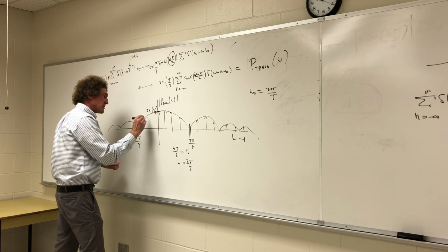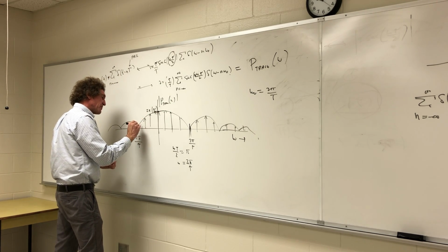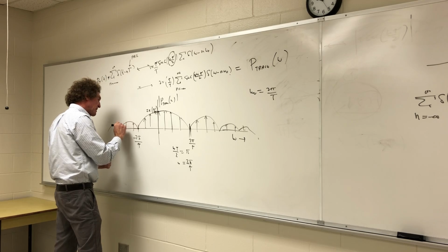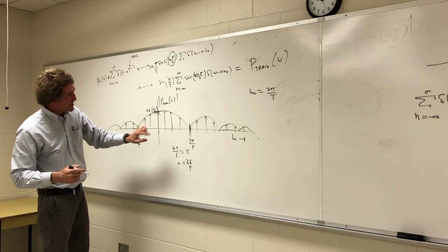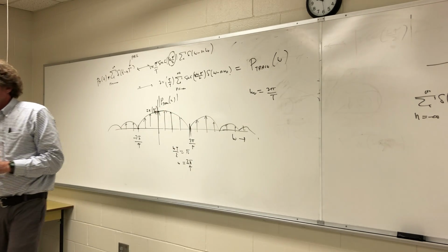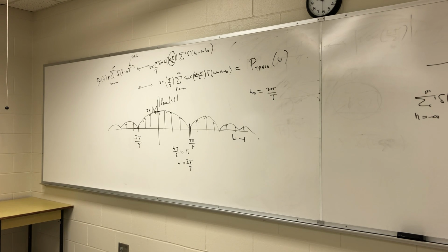Now I'm going to talk about something that's very, very important next. And this one you don't want to mess up. So that's the envelope, but that's really what we're going to see if we were in the spectral domain and we had the ability to capture a large amount of a waveform and do a fast Fourier transform and then scale it accordingly. We'll get into scaling and all that in a bit. You remember where we took a continuous time Fourier transform and we got the information.